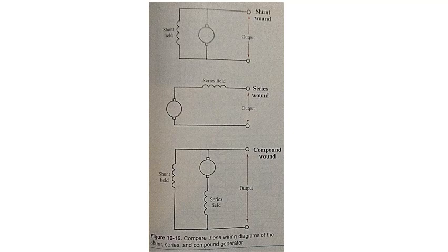If both act in the same direction or polarity, an increase in load causes the increase of current in the series coils. This increase in current would increase the magnetic field and the terminal voltage of the output. The fields are said to be additive. The resulting field would be the sum of both coils. However, the current through the series winding can produce magnetic saturation of the core. This saturation results in a decrease of voltage as the load increases.